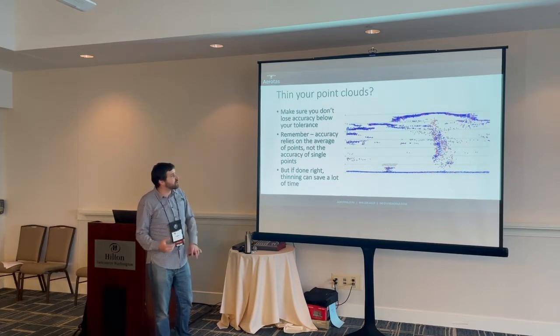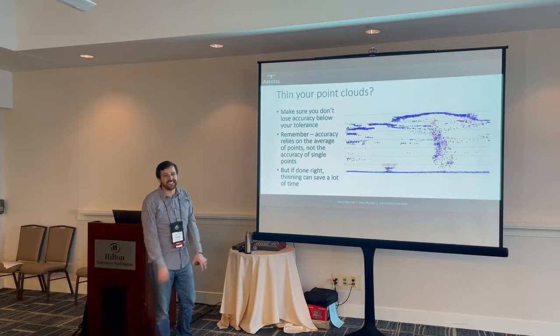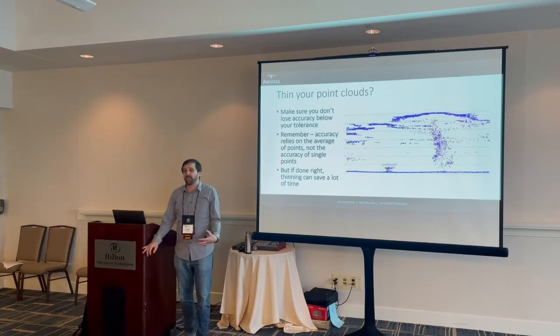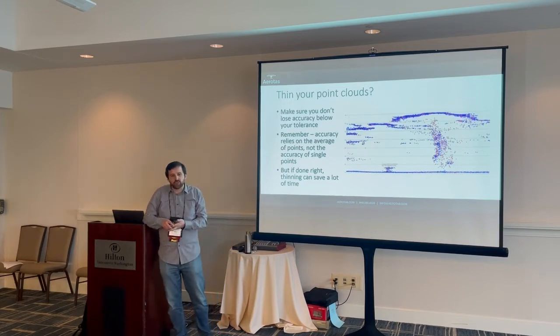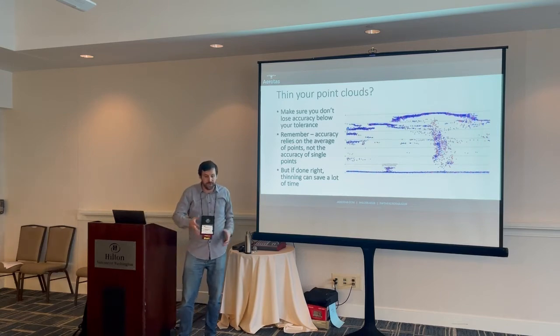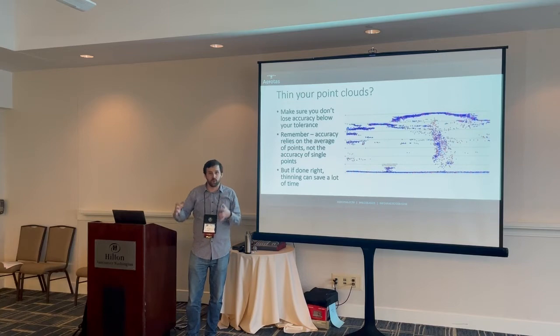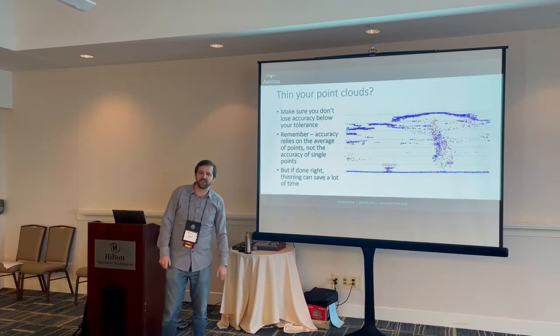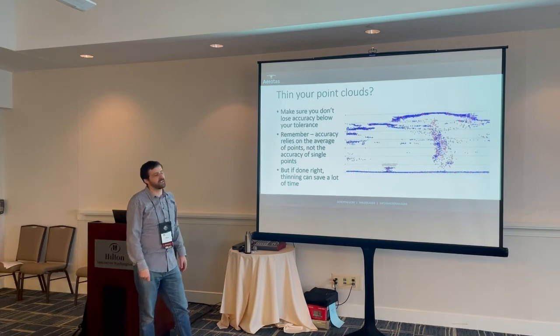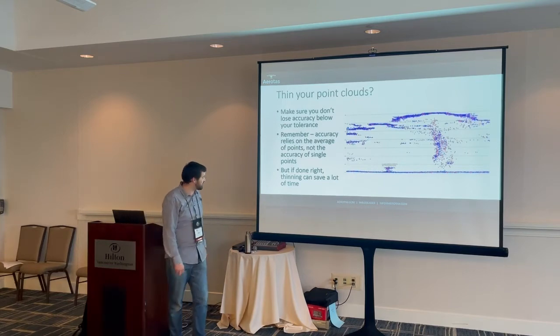Other methodologies you can use instead of thinning is just straight tiling. A lot of people will tile their point clouds, break them up into smaller chunks and process them one at a time. That has its own trade-offs too. It creates a lot more overhead and work. You have to work on this tile and then close it, reopen the next one, work on it separately, and then at some point maybe open them both up to make sure that all of your work aligns properly at the seams and everything. So tiling is another option for dealing with very, very large file sizes.